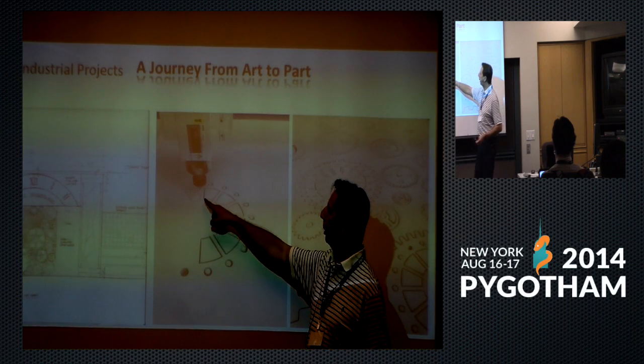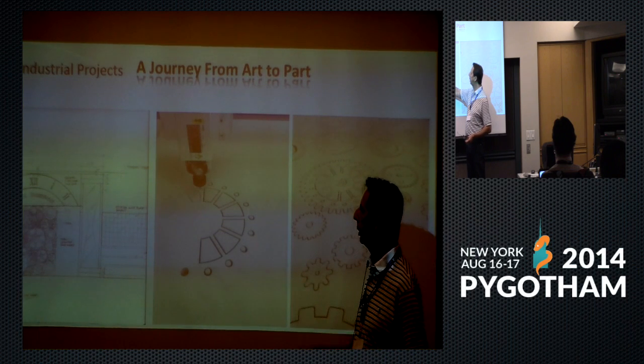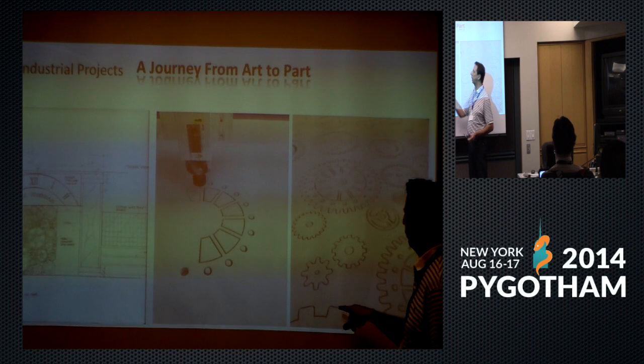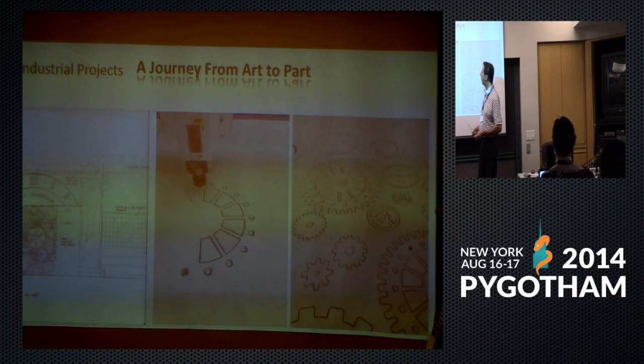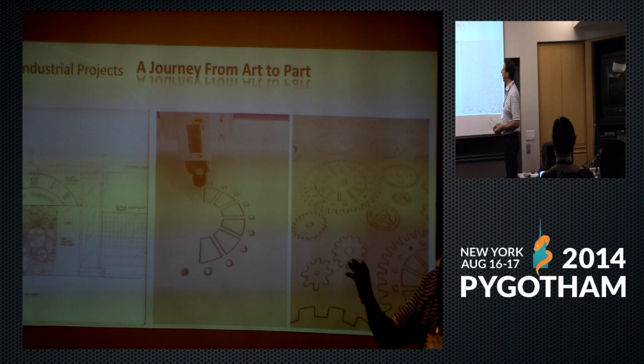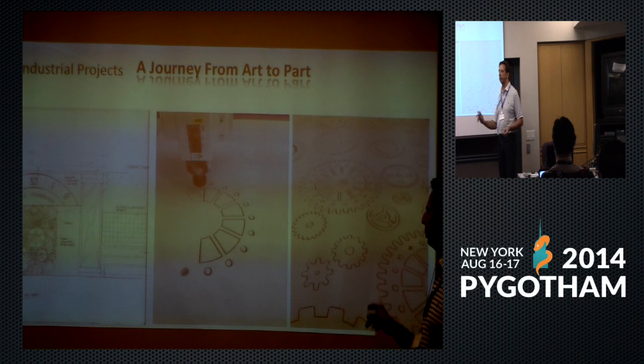Here you see now the cutter exposed. The spindle turns at about 18,000 RPM, rotations per minute, and it cuts into a foam block, very hard foam, which is made for sign makers. And it cuts pieces out, and at the end of the day, when it's done, well, end of the day is indicating a long time. It actually takes an hour to cut a whole 4x8 sheet with all this detail. Then it can be taken out, glued up on a surface, and painted.